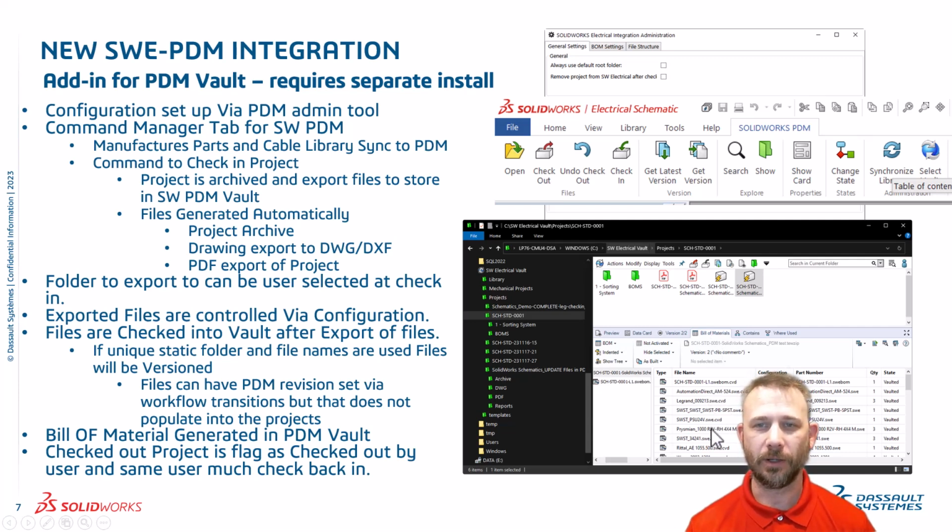And it's going to list out all of the virtual documents for that file, right? So it's going to build out that bill of material for you, give you quantities based off that information, and it's available there for you. Now, one thing to keep in mind is that the bill of material is hard-coded. Unfortunately, we cannot change that, but you do get that information in here, okay?